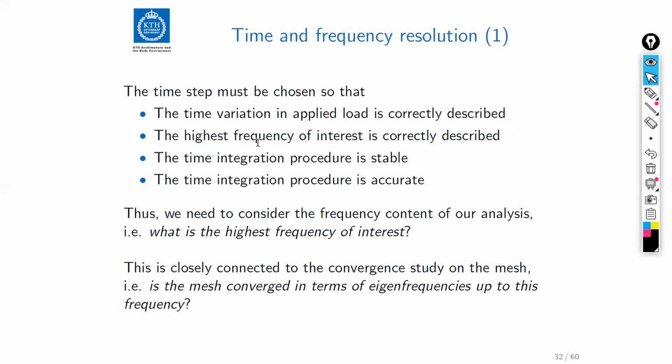If we use the modal approach to the analysis, then this inherently limits the frequency range to the modes that we choose. But if we are doing a time integration, the frequency range will be defined by how we define the time step and the total time of the analysis.